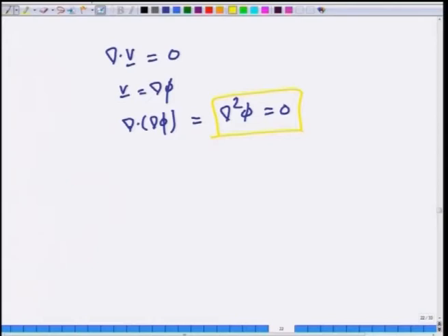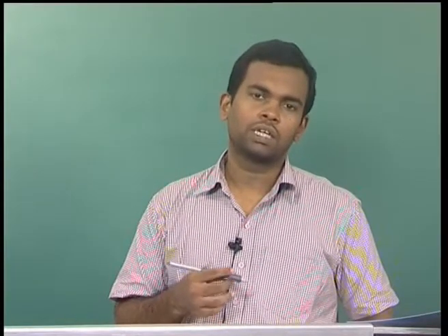And we said that instead of solving for the Laplace equation, we will use the superposition idea, wherein we have some simple flow patterns such as uniform flow, flow due to a source or a sink, flow due to a line vortex, flow due to a dipole and so on, and by superposing various simple flows, we were able to generate more complex flows, and we said that we could simulate or mimic potential flow past a circular cylinder by simply superposing a uniform flow with a dipole, okay, at the origin.